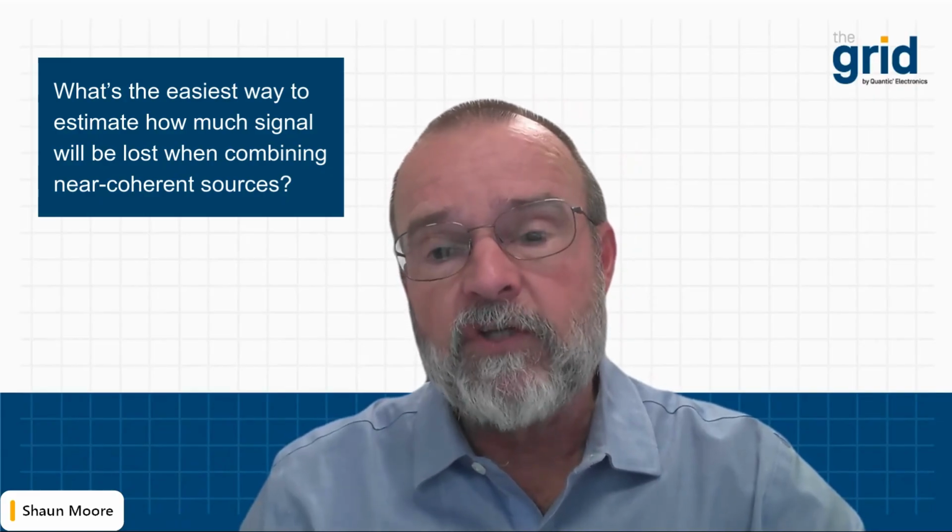Take the RMS value of the phase error between the signals you're combining, take half that angle, and take the sine squared of it. That will give you the percentage of power that is lost. So it's a fairly simple equation. Like I said, the half sine squared gives you a very close estimate of exactly how much power will be dissipated as heat or reflected energy within the power combiner.